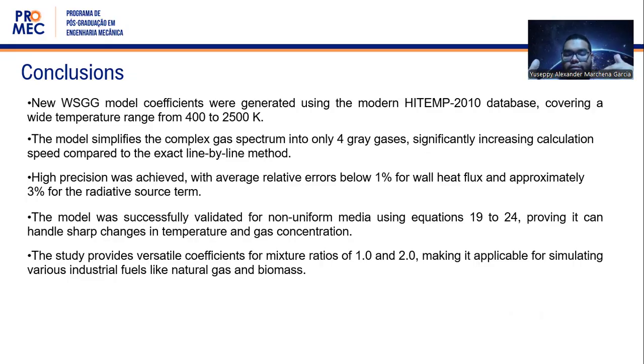We can see that the WSGG results are very accurate compared with the L by L reference solution. The results showed a remarkable consistency of the model, with errors of the order of 5% maximum and 2% average, even under severe conditions with large thermal and compositional variations.